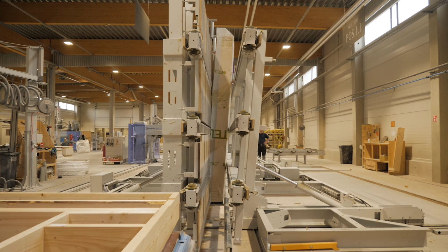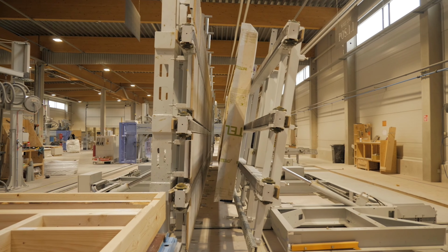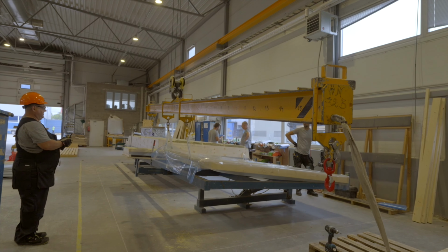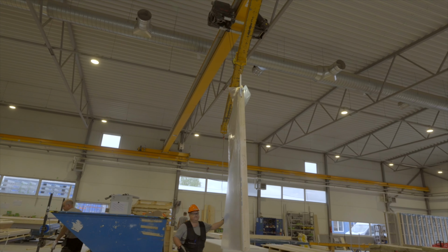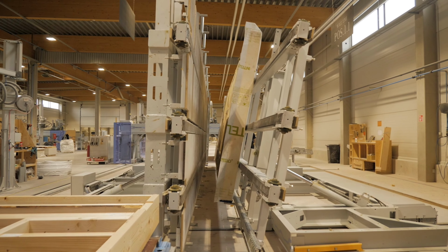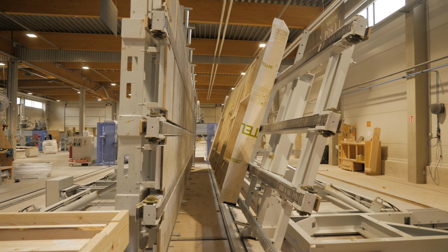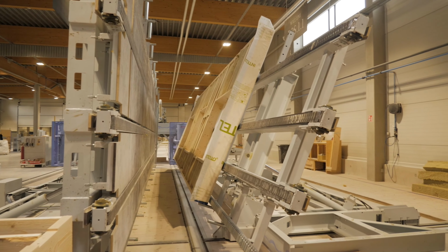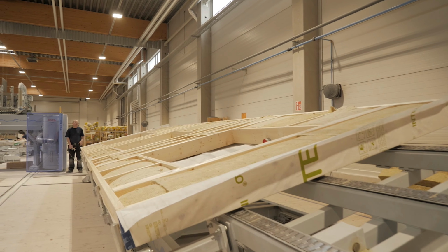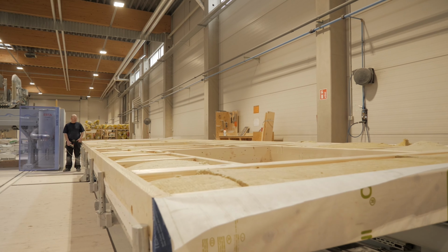There are two ways to turn over: either lift the elements with a crane or use the so-called butterfly tables. Crane lifting is relatively slow and requires several people to work together. That is why many manufacturers use butterfly tables. This means two adjacent work tables that can be lifted by their edges so that in a vertical position they meet, and the finished structure moves from one table to the other in a turned position.